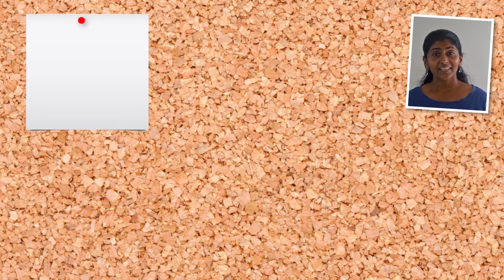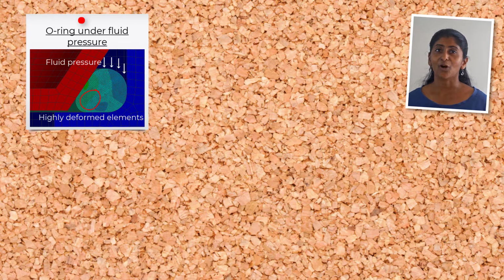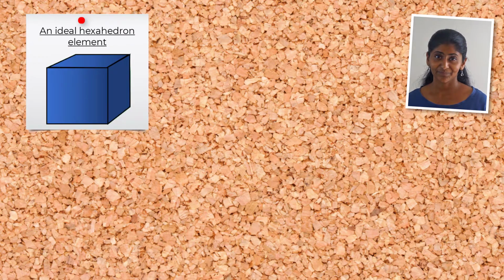One of the frequently encountered errors when using hyperelastic materials is the excessive element distortion error. Due to the highly nonlinear nature of the simulations, certain local regions of the model may undergo excessive deformation. This in turn may lead to a non-physical shape of certain elements in the mesh. For example, consider the element shown here.